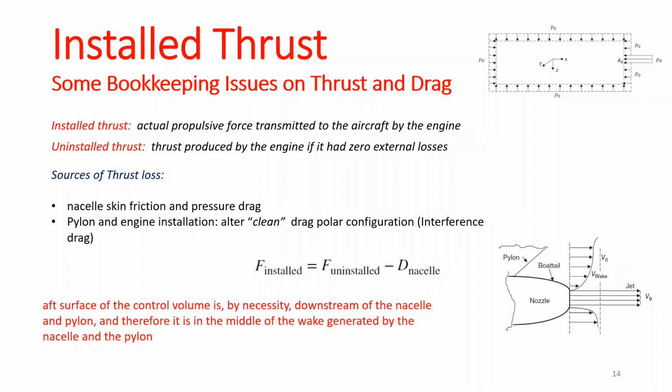And we did calculate the momentum as m dot, rho naught v naught multiplied by the difference of this area by this, multiplied by the v naught velocity, right? We cannot do that anymore because the velocity is going to have a distribution, right? This means that your calculations are going to be a little more complicated.